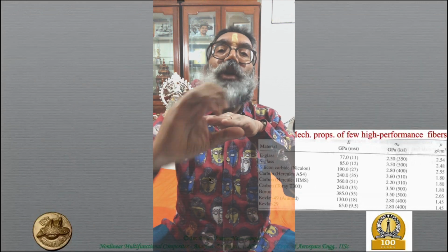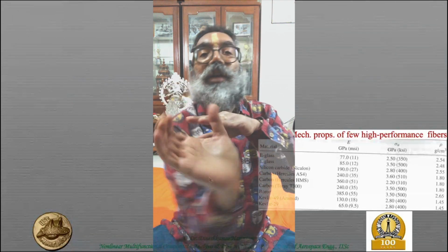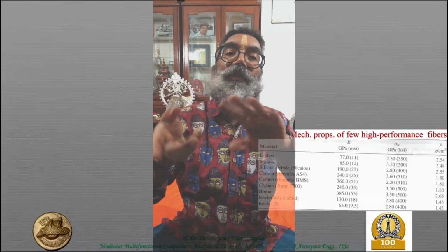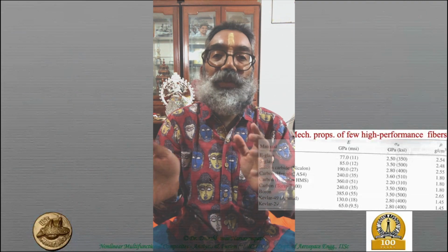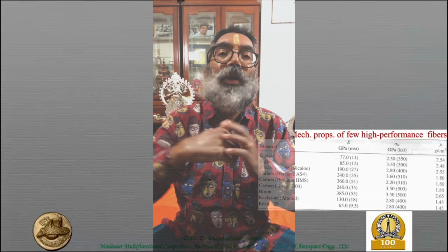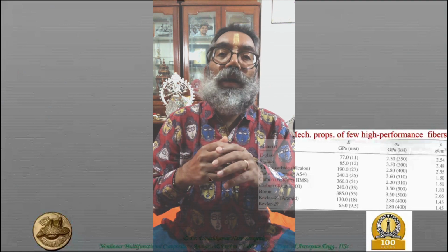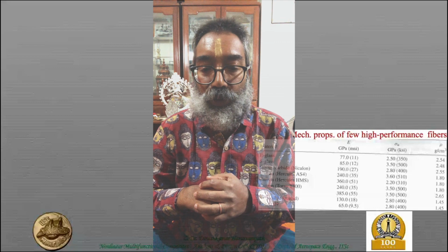For example, you can think of the torsional load. So if the torsion is in this direction, one of them will be under tension, the other will be under compression. But if the torsion direction changes, then you will have the vice versa. The one which was undergoing tension now undergoes compression. So you have to be prepared for both these regimes of operation, either in different parts of the flight mission that you are talking about, or it could be during a particular mission itself because of the dynamic loads which are vibratory in nature and therefore changing signs. Does that answer?